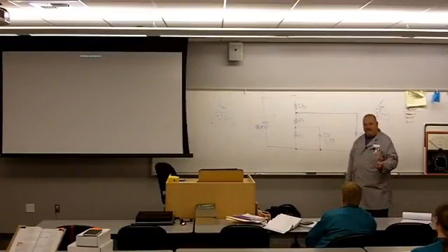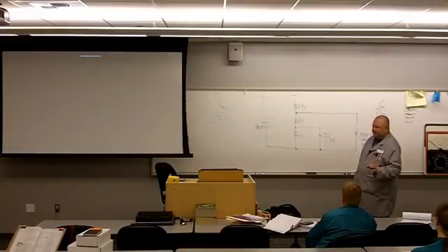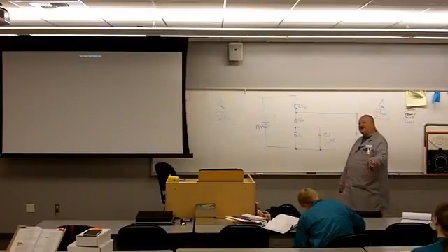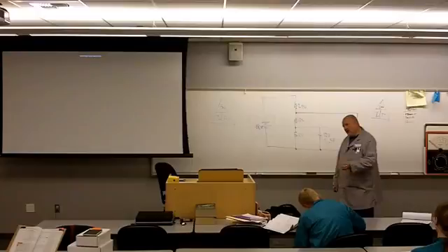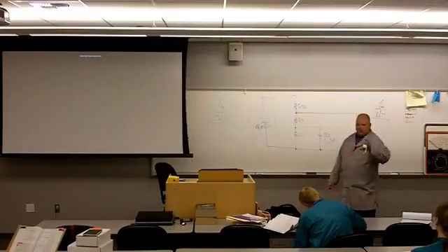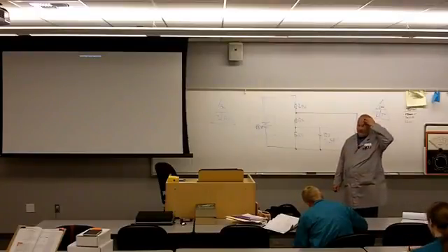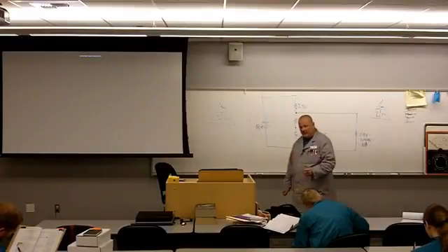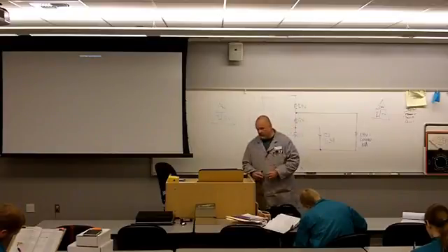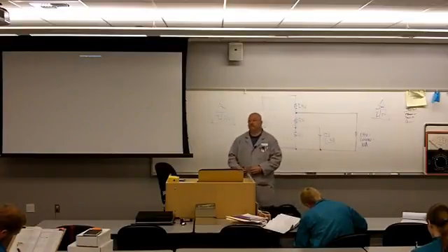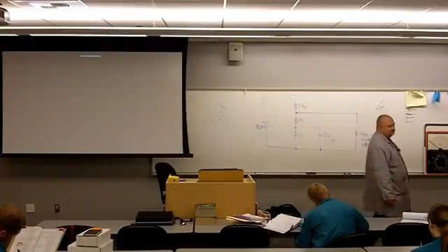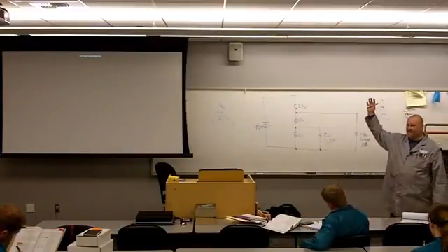The thumb rule is, you ready for this? The bleeder current needs to be 1/10 of the total load current. The bleeder current needs to be 1/10 of the total load current. How many of you buy that? You better buy it. I just sold it to you.